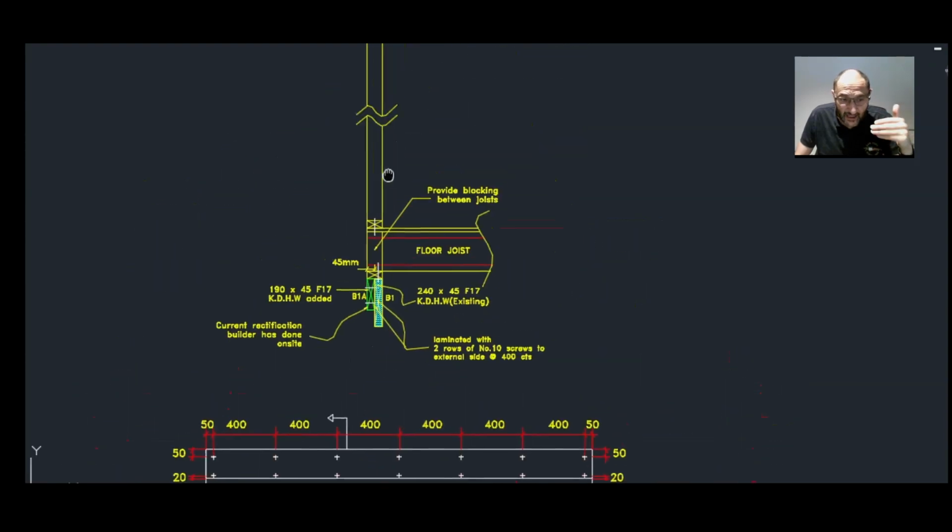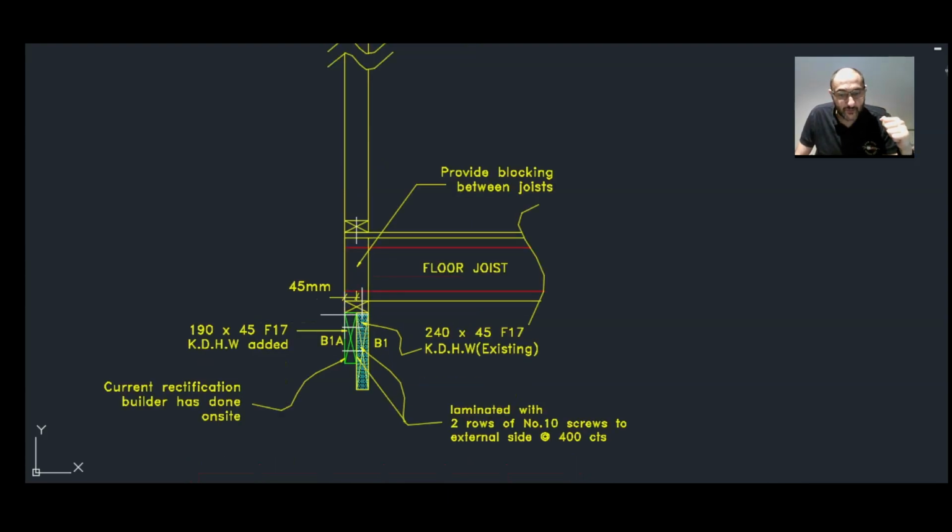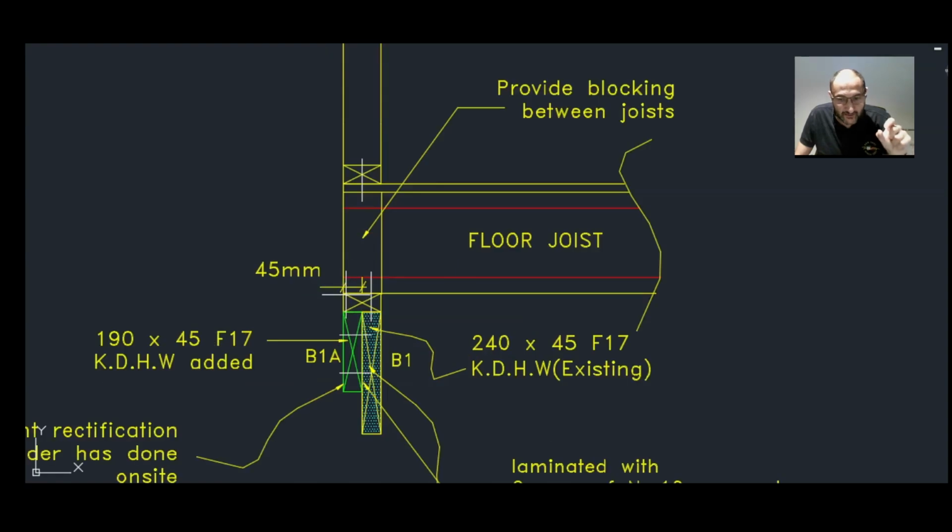Does the upper wall carry any studs which support a girder truss load, or maybe a large point load? So you need to check for that. If so, then we probably would need to take the eccentricity into account. If we assume a conservative point load at the edge of the plate, then we will need to check if it will come out at the ends or not.